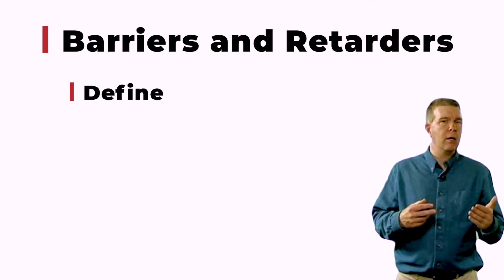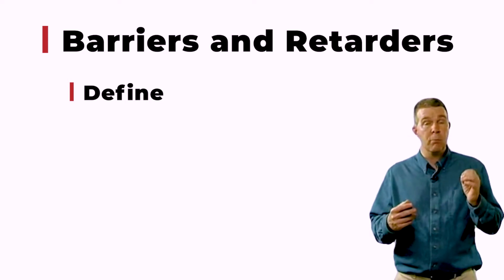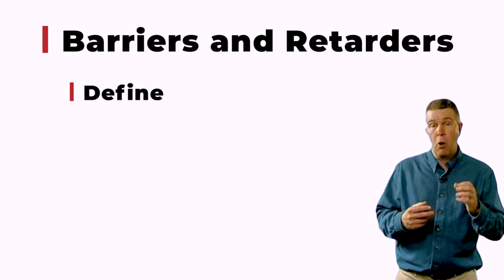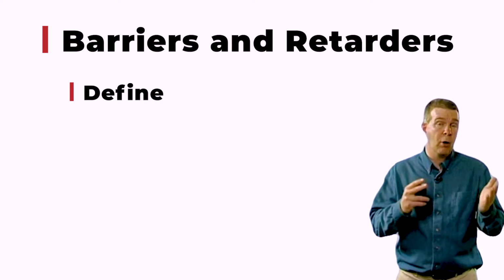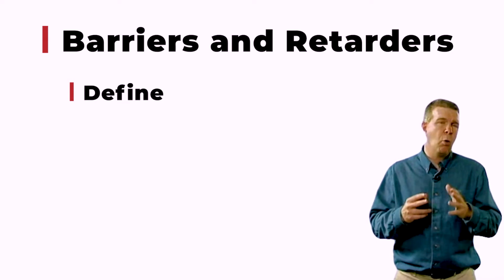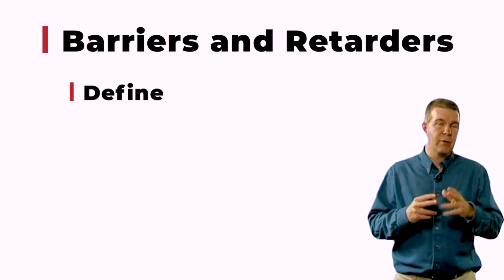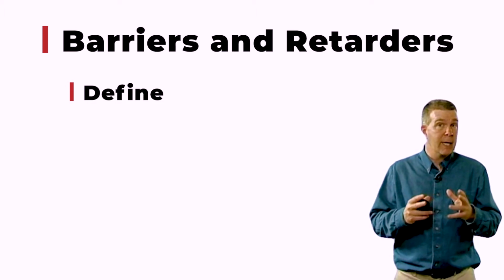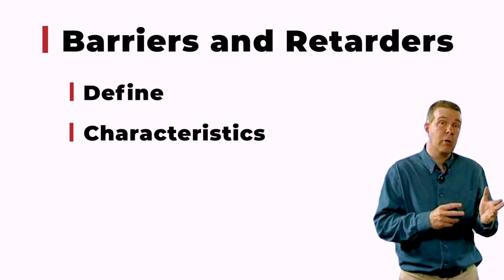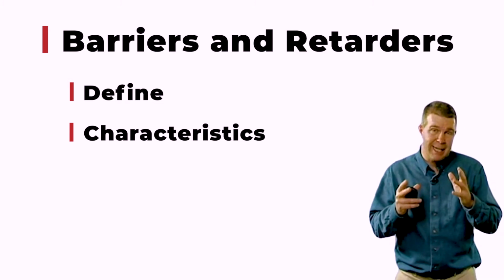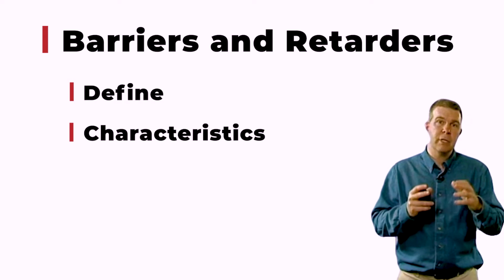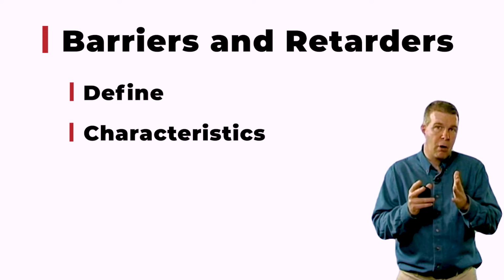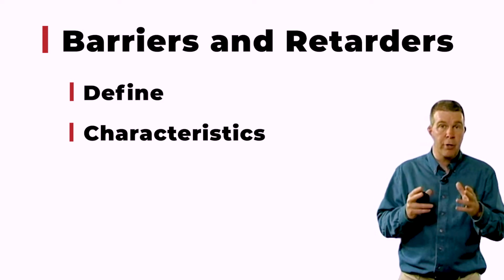It's important to understand why one works differently than the other. What's most important to understand is that we don't use a vapor barrier or an air barrier on both sides of our SIP panel. We always want to have our assembly designed so that it has the capacity to dry in one direction or the other. Again, remember what we talked about. It's just as important, if not more important, for the assembly to have a system to dry, for the water to get out. And it's that capacity to dry which has to go in one direction or the other, or you're going to have problems.